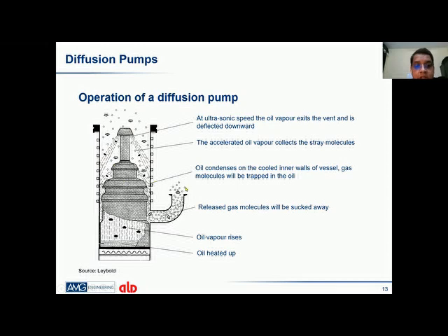So it will not be directly connected to the atmosphere. All these pumps will work in series. This diffusion pump will be connected to the booster, and the booster will be connected to the vane pump.